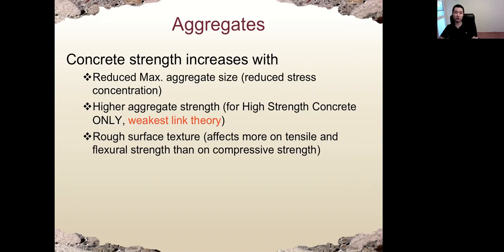Increasing the strength of aggregate will also increase the strength of concrete. Now this is for high strength concrete only. For normal concrete, increasing the strength of aggregate could not increase the strength of concrete. So why? That's the reason.